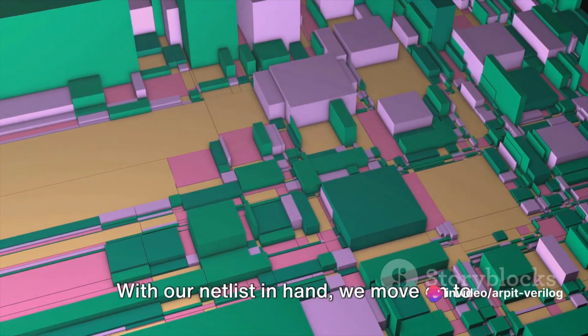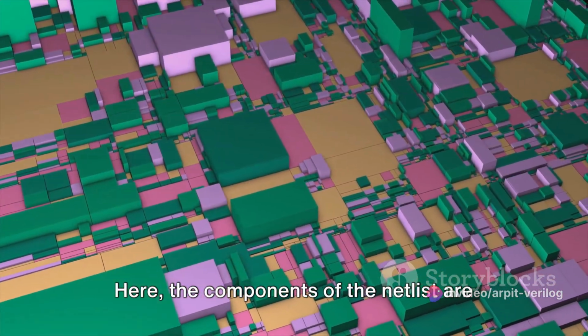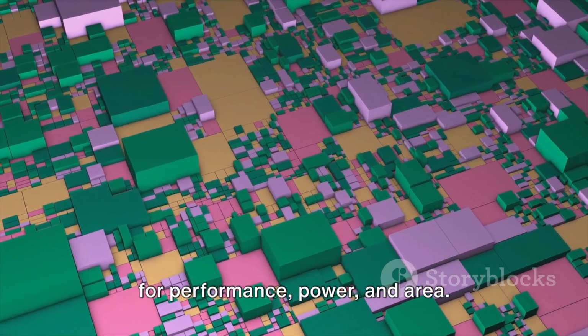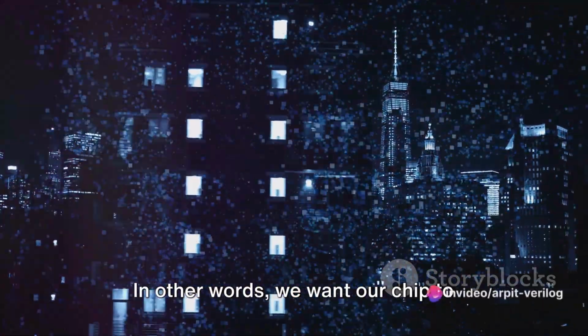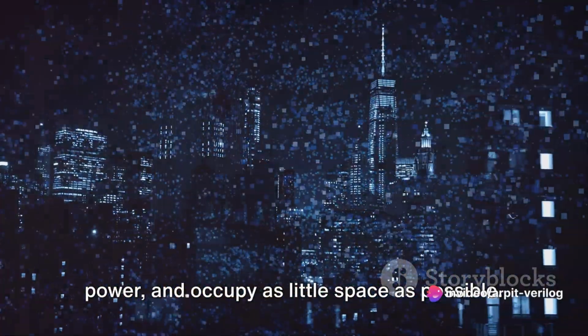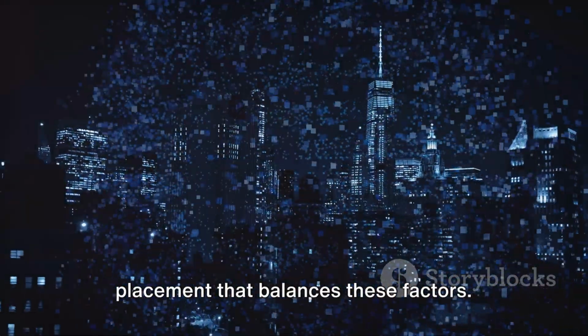With our netlist in hand, we move on to the next step, placement. Here, the components of the netlist are arranged onto the chip. This arrangement needs to be optimized for performance, power, and area. In other words, we want our chip to function efficiently, consume minimal power, and occupy as little space as possible. Algorithms are used to find the best placement that balances these factors.